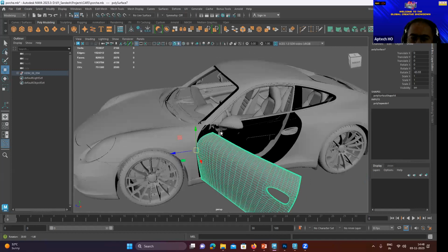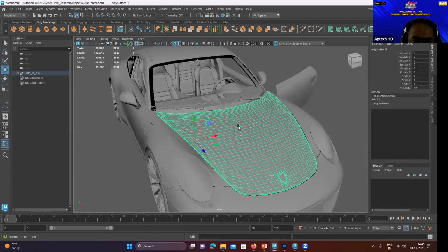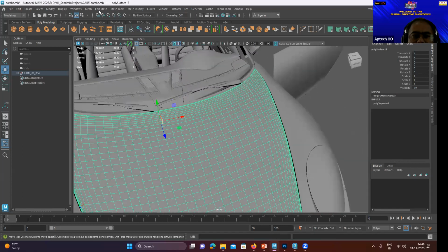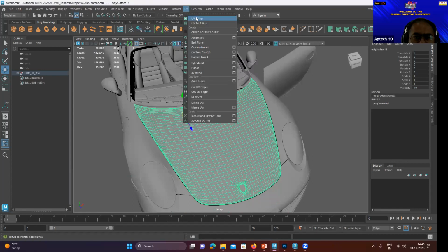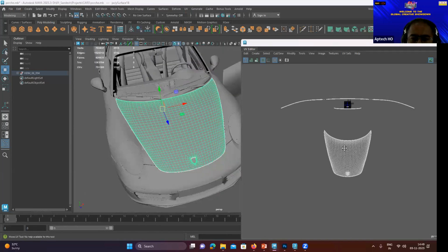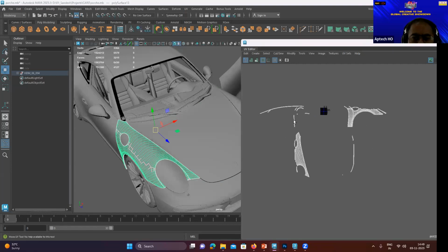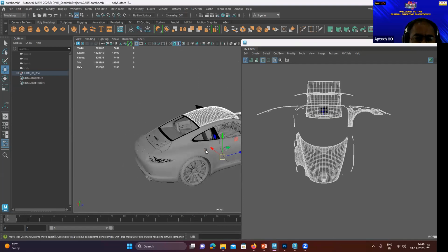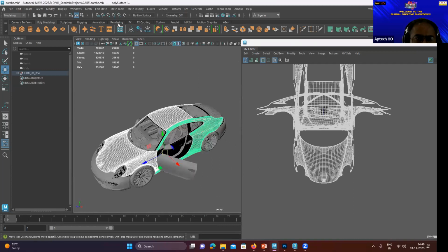And it's basically a simple rule, a thumb rule of modeling, that if you separate it out, you can easily do UV unwrapping on that particular object as well. Suppose if I click on the UV editor, you can see these are separate UVs. You can arrange the UVs accordingly, right? So what if this car is made up of a single mesh?